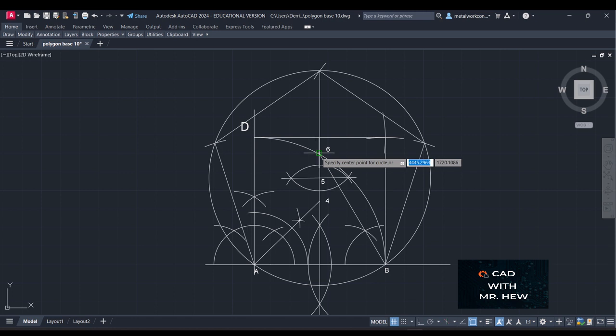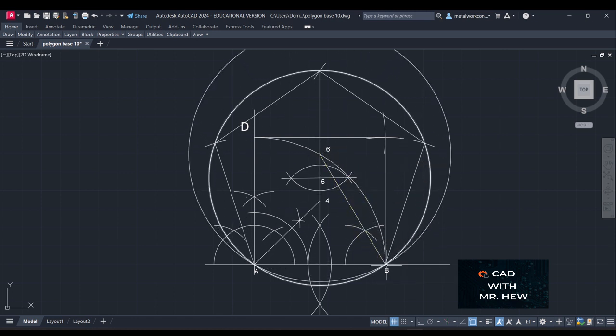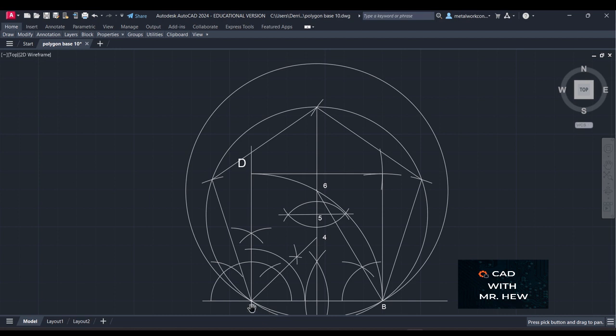So we would go compass at 6, radius B, good, and that would be our circle. And we just repeat the same process, right? So we could take the radius AB and mark it along the circle which was drawn with the compass point at 6. All right. So we're going to mark the arcs on the circle, to construct this circle. All right, is that clear? And the radius will be the length of the side AB.